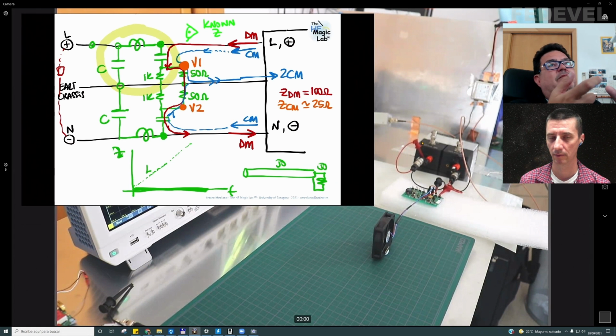In my opinion, the problem is that the routing of the different points of the circuit to the switch must be very well done to avoid non-equilibrated paths for the common mode. Because with this kind of switching activities, you can create a non-symmetrical behavior for the common mode. But there are good line impedance stabilization networks working in the market with this.